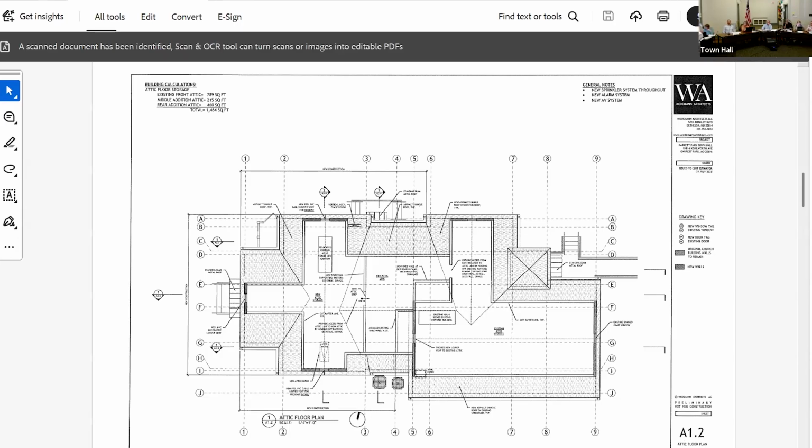I've had conversations about that, and I've had some experience adding insulation to 100-year-old buildings. Sometimes you can do more damage because of the vapor drive that's in the wall. So if we do a complete removal of the siding in the end, we would have that opportunity. We could drill some holes in the sheathing and add insulation. The staff at the HPC said that we should be cautious about doing that because it can create a vapor drive issue.